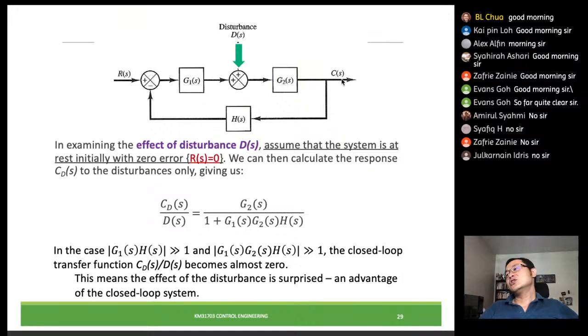the signal as such. So when this is removed, you can now reorder your view, such that this is your input and this is your feed forward. Then your feedback will now go through H and G1. Can you see that? It would become H and G1 as your feedback.